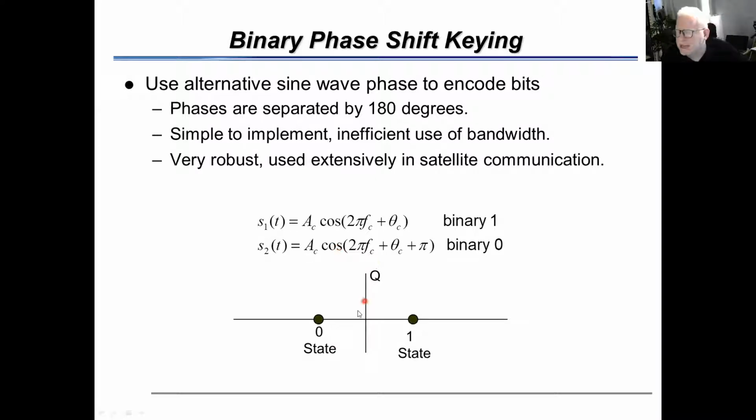And we represent the 0 with a carrier with a certain constant amplitude and a phase of 180. That's why in the constellation diagram, we introduce this point here, because this direction of the x-axis represents the 0 angle, or what we sometimes call I, the in-phase. This represents the 90-degree angle, or what we call Q, the quadrature. And then this is 180 and this is 270.